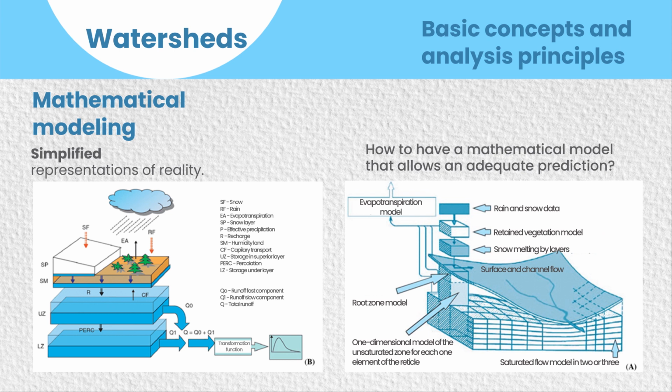On the slide you can find a classic representation widely used in hydrology, which is to represent the basins and the water system using tanks. Of course, the reality is not that we have tanks. This is just a conceptual model that makes it easier for us to represent. We like tanks because they have control volumes. They allow us to connect inputs and outputs, and they are generally simple. So, using tanks helps us simplify reality. This is just one example of a tank-based model build, but of course there are different types of conceptual models.